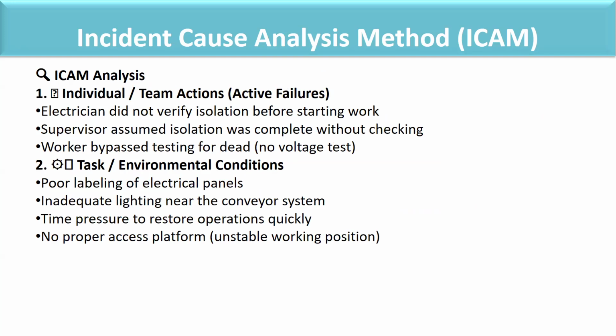Now over here, ICAM analysis. Now we apply the ICAM methodology to this particular accident. Let's say we have the report for the individual. What we will see over here, team actions, active failures: the electrician didn't verify isolation before starting work. Supervisors assumed isolation was complete without checking.